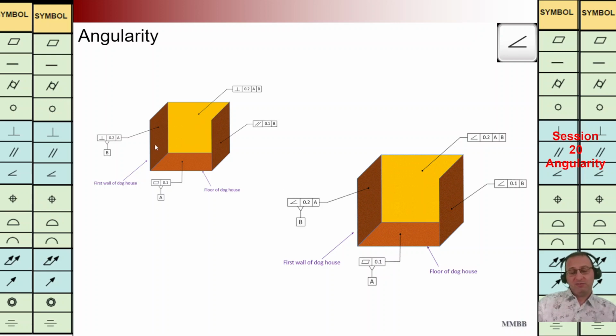At the beginning, for example, this plane on the left hand side is perpendicular to A, plane B. It means we are going to have two boundaries perpendicular to A, and the distance between these two is 0.2. It has the same meaning as the perpendicularity. For perpendicularity, we are going to have two planes perpendicular to A, and this wavy surface should be in that interval. That's why these two figures have the same meanings.